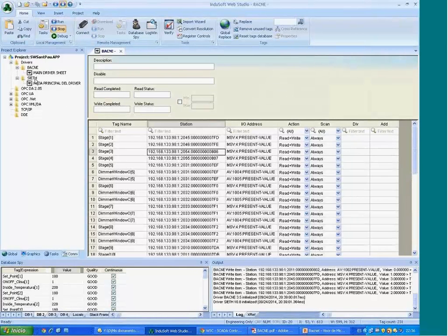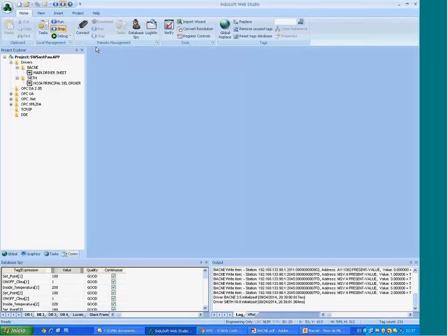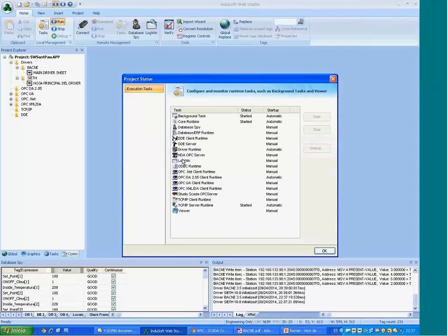And also we have a Siemens PLC driver running, okay? And let's see the result of running InduSoft as a terminal server. I will run InduSoft without the viewer, and now each of the sessions will run its own viewer. I'm running it manually.